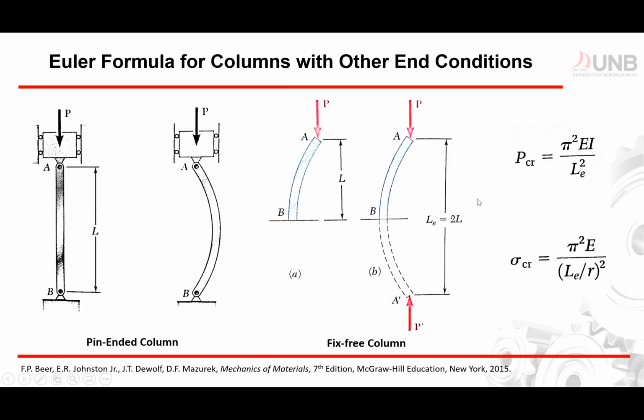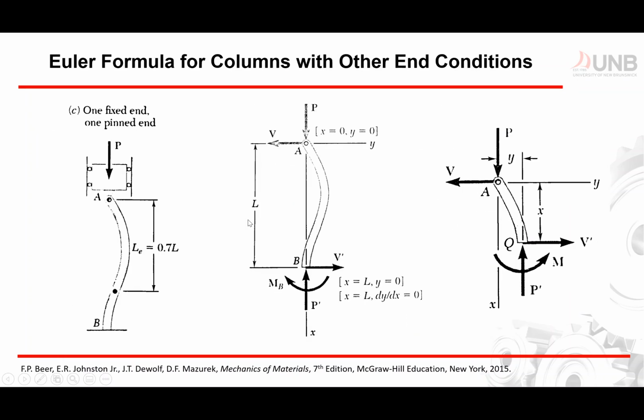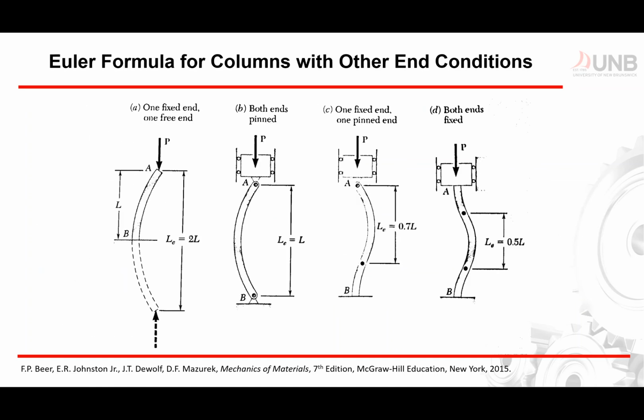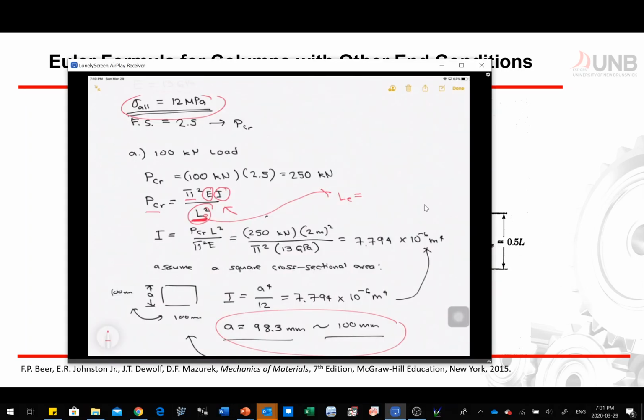Fixed at both ends, so LE is equal to 0.5L. Which means I could change this into LE is equal to 0.5L, and then everything will be the same. It's just the value of your L. All the calculations will be the same.